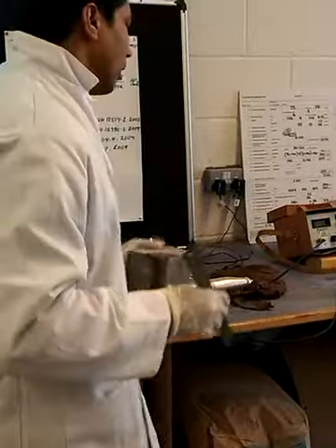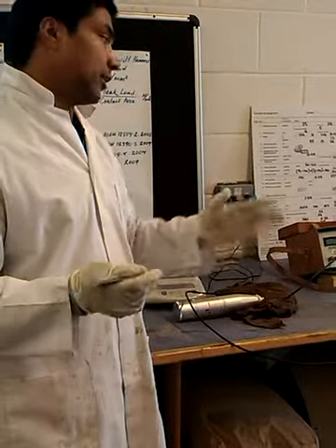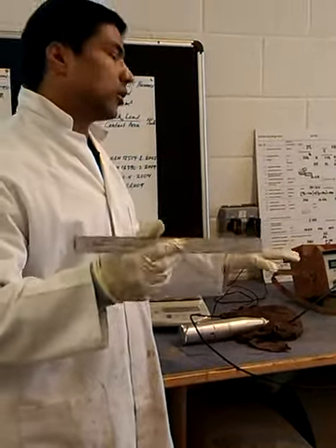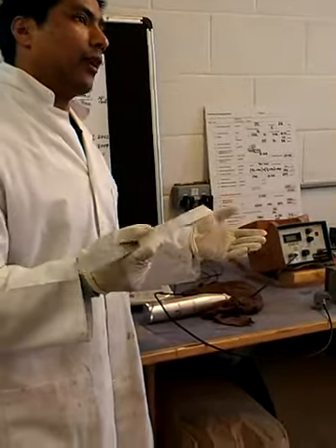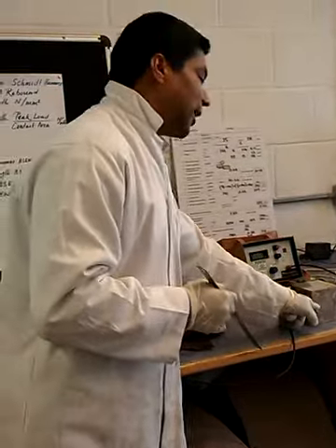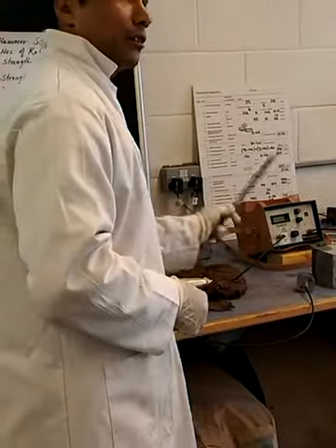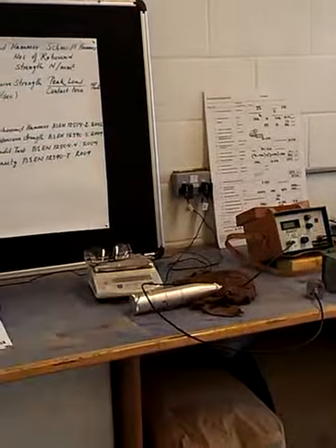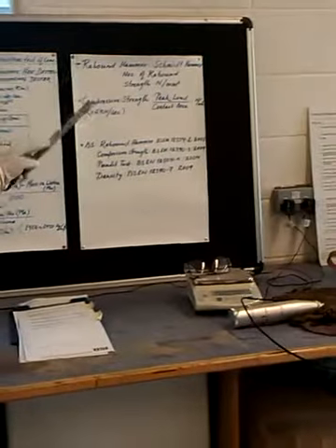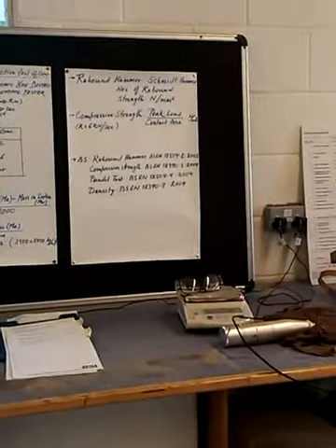So when you are getting values that are consistent, for example 20, 20.5, 20.4, something like that, it's okay. But if the values jump to 30, or 20, then 30, 35, it means there is some defect inside the cube, because it has a gap and the path is deviating, right? That is how it will detect the gaps or cracks inside the concrete. So you have two purposes for the Pundit. One is to know the quality of the concrete, and the other is to detect cracks or gaps inside the concrete. That is the use of the Pundit.